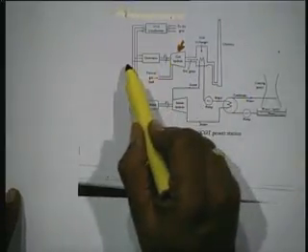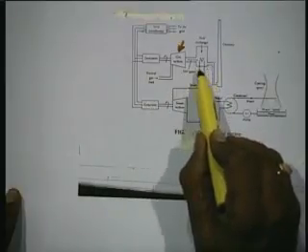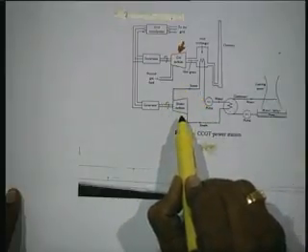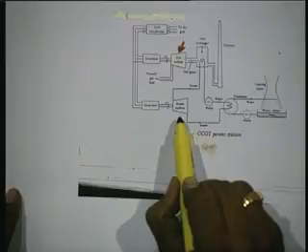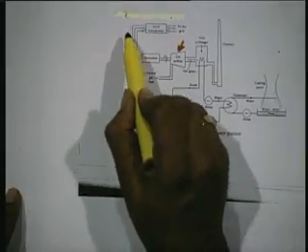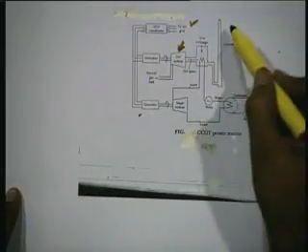The gas runs the generator, but the waste heat will be utilized here to produce steam, and that steam is taken to the steam turbine. And again we generate power in the generator, and both these powers are combined and fed to the grid. There is a chimney, of course, here,